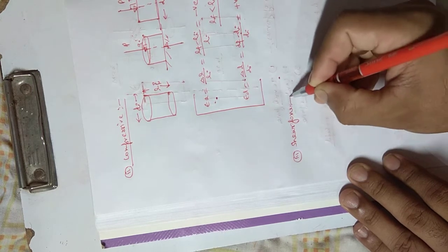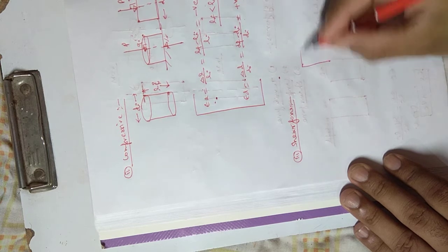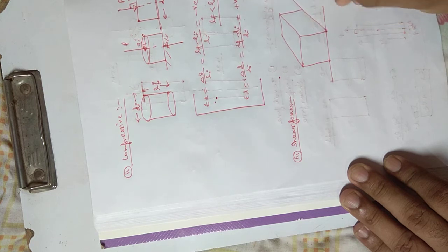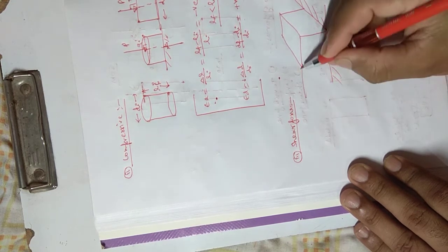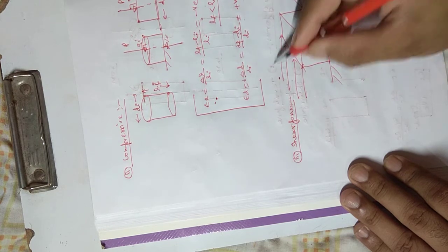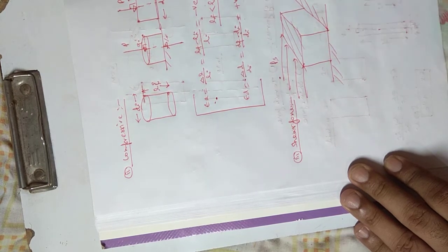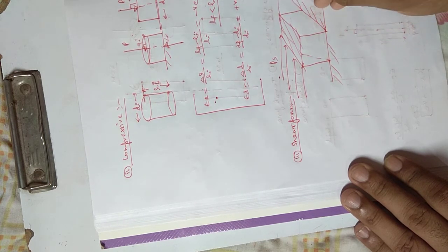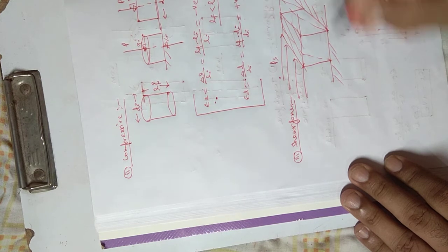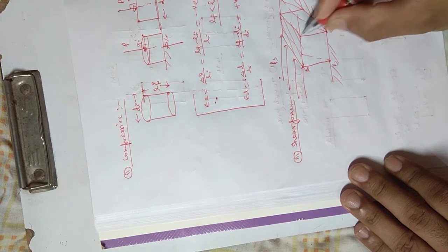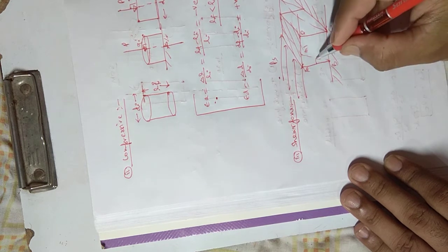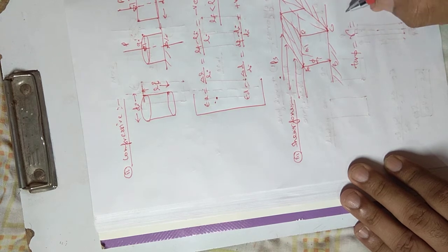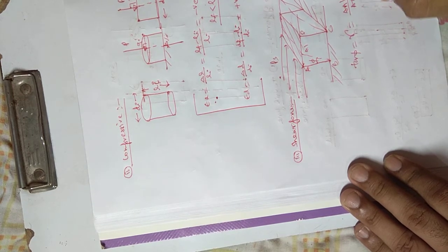Shear force tries to shear off the sections. It means in this case the load acts parallel to the cross section. Like friction force is our shear force. The shear force is the force which acts parallel to the cross section. This is my cross section. Suppose it is fixed at the base, so it will try to tilt this member. It will tilt like this. Suppose these are my A, B, C and D. So A dash. This is my phi. So tan phi is the shear strain, A dash over AB.